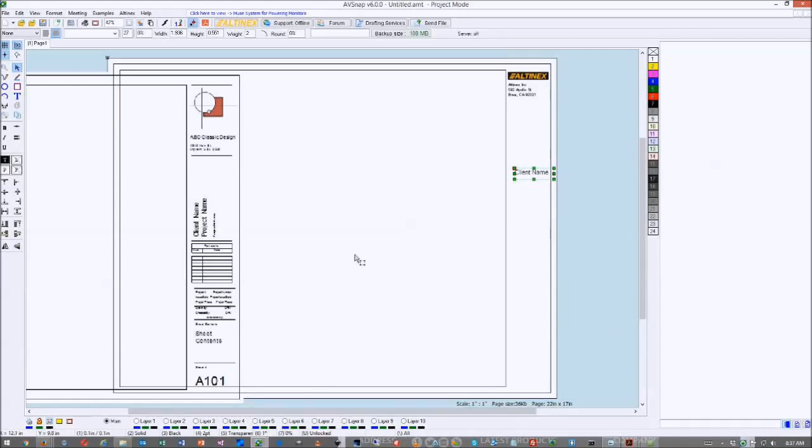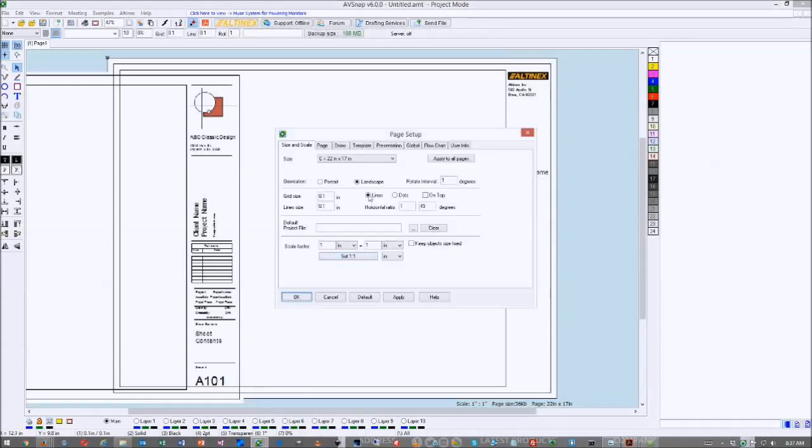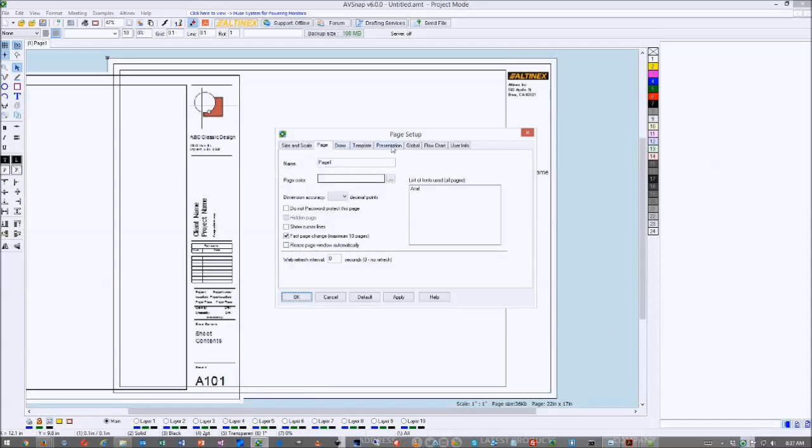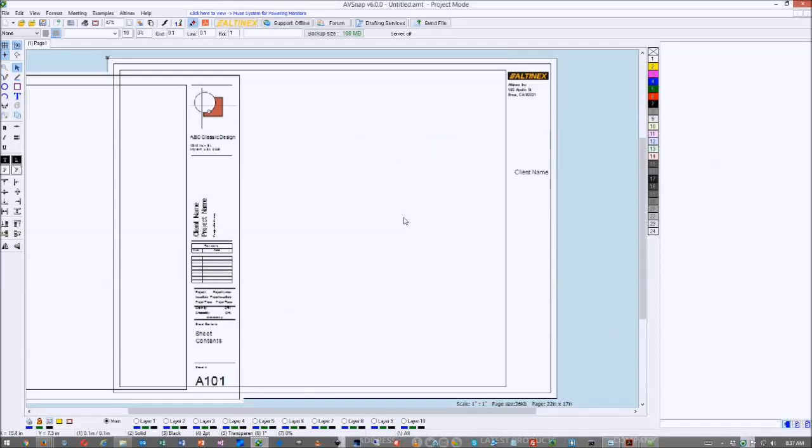Or you can always double click on a page, and you can say what would be the rotation angle. So you can preset under the global settings, okay? The other thing you can do is to use a rotate tool, but that's not as precise. So I'm going to go ahead and set this to 90 degrees.